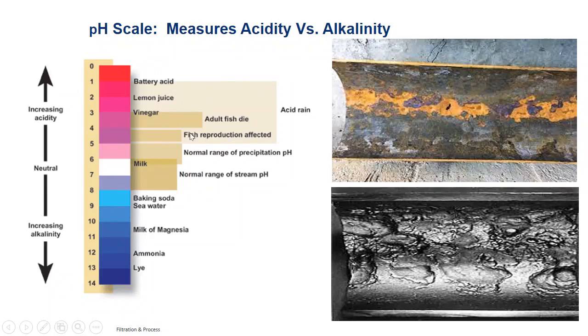So realize pH plays a very important role in whether or not we will form scale deposits and whether or not we'll be able to have a lack of corrosion going on with our metals. And notice that we use the words increasing alkalinity here. Alkalinity is part of that carbonate, bicarbonate, CO2 buffer system. This is Tums in the water. This is the buffering capacity of water, how much acid it can absorb. You have to consume your alkalinity to make water more acidic. And this is increased acidity.